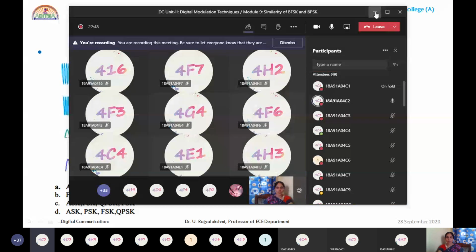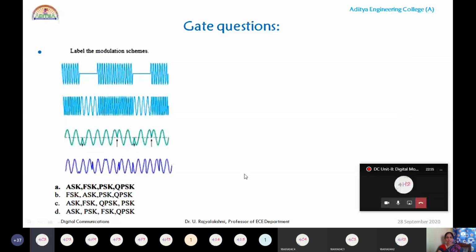Yes, ma'am. Okay, please listen to my question. Can you see 4 waveforms here? Yes, ma'am. Please tell me, these are the outputs for which kind of keying techniques? First one, please tell me. ASK, ma'am. Why ASK? Ac cos omega c t for input 1, ma'am. Yes, for input 1, Ac cos omega c t. And you have 0 magnitude for? Input 0, ma'am. Yes, very good. Next, second one is for?